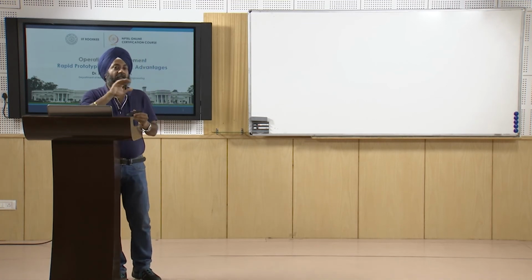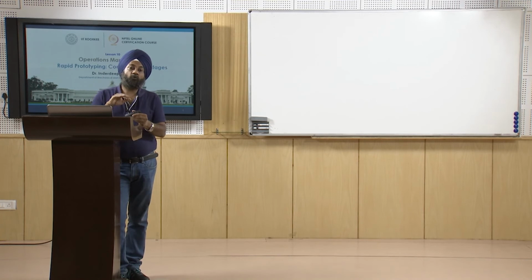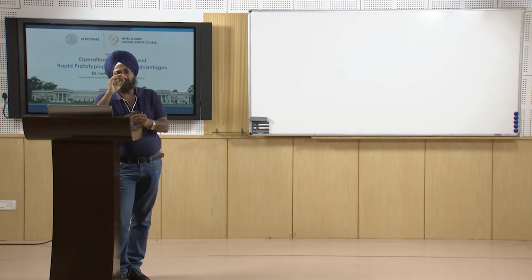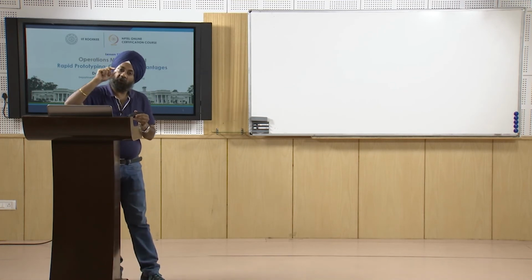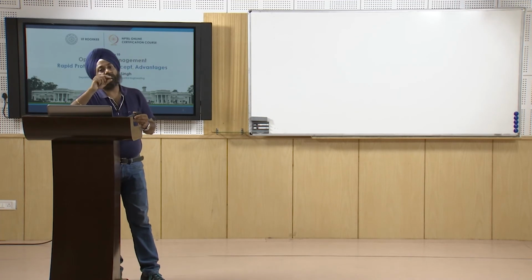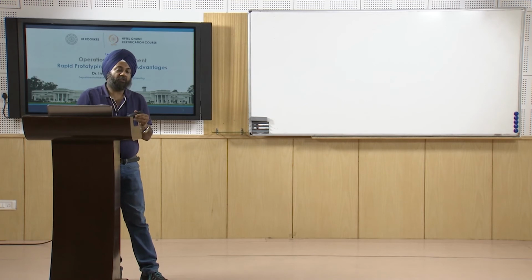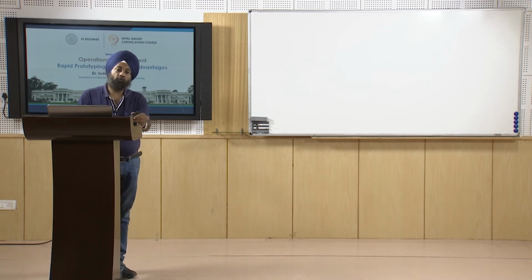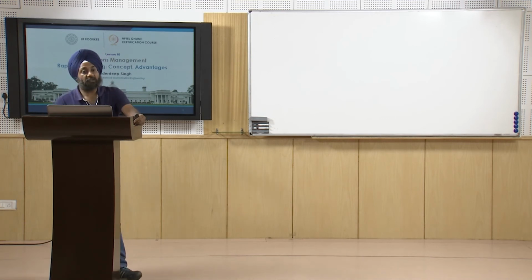So the third stage is the decision regarding the number of layers. If we use more layers, the thickness will be less. If we go for fewer layers, the thickness of each individual layer will be more. Depending upon the technology that we are adopting, we do the slicing of the product into layers. That is done in the third stage.